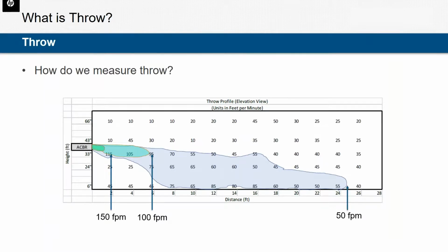But you'll notice that the 50 feet per minute isovel is not as well defined. That's because 50 is really pushing at the boundary to the point where other factors within the room, whether it be occupants or just someone walking across the room, can affect that 50 feet per minute isovel. It's pretty fragile. We'll even see some points here where the velocity dropped to 45 and then went back up to 55. That's just due to turbulence of the airstream.